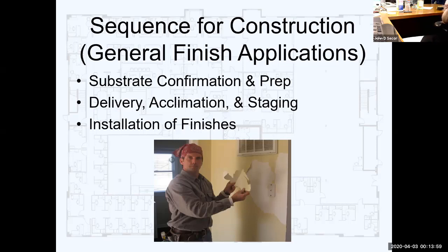The reason is that the wood will acclimate, will swell, or will contract based upon the environment that it's placed in. So you don't want to install it and have it buckle because it's expanded when it shouldn't have. All right, so all those installation pieces are important.